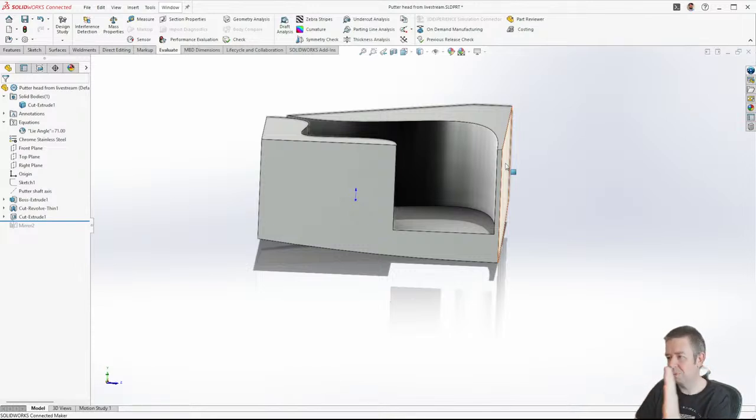Because we want it to actually be roughly flat with the putter, we have to put a 4-degree or so upward tilt on this thing. We have to put slightly more on it because the shaft's going to be back here, which means the player's going to lean it forwards a bit more. So we'll probably put a 5-degree lean onto this.